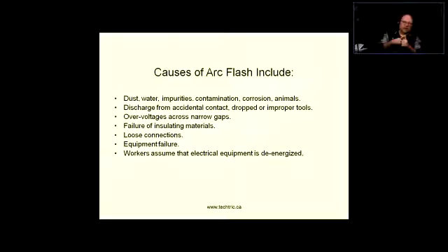But when it comes to power, if you perform terminations that are not proper, all kinds of sparking and arcing can happen right at the connection, right at the termination. Equipment failure, well, self-explanatory, and here is the one that takes the cake in a lot of cases. Unfortunately, workers that assume that electrical equipment is de-energized.